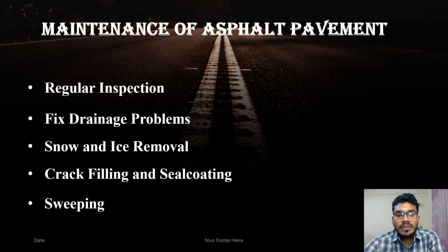The trapped water under the surface resulting from the freeze-thaw cycle, combined with the weight of the traffic and high temperature, can degrade the road. Regular snow and ice removal is the ideal way of maintenance. Then crack filling and seal coating. If an asphalt road has a crack, water can get through it and weaken the road. Moreover, a heavy load of vehicles can also cause the cracks to widen.